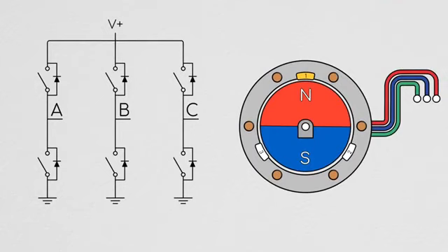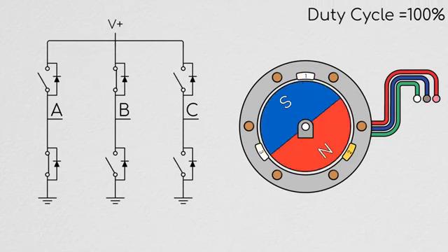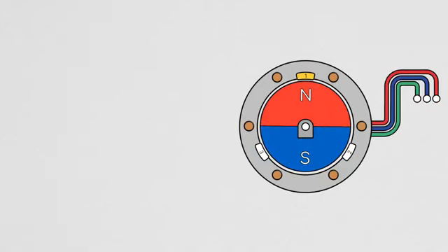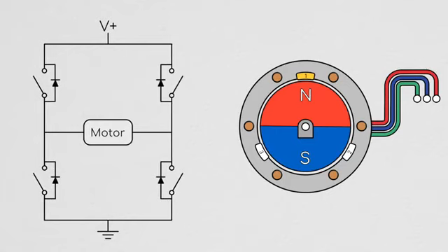All of the switching methods we're going to talk about this episode can be used with block commutation, meaning again that there will only be one phase connected to high and one phase grounded at a time. Because for this episode we're only going to be using two phases at a time, we're actually going to temporarily ignore the third leg of the H-bridge while we analyze the current dynamics of the motor. The topics we're talking about will hold true for a 3/2 bridge system. However, I find that it's easier to show and to understand if we're only looking at two of them.